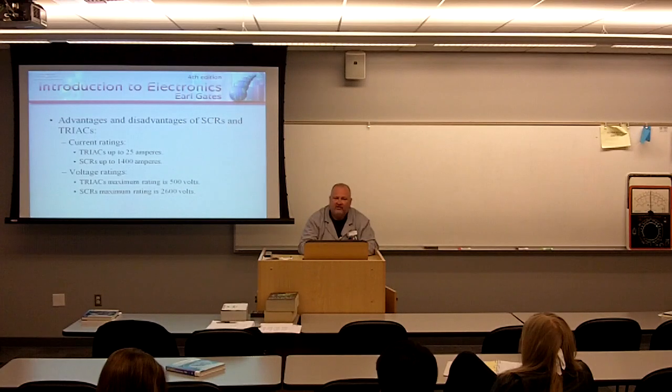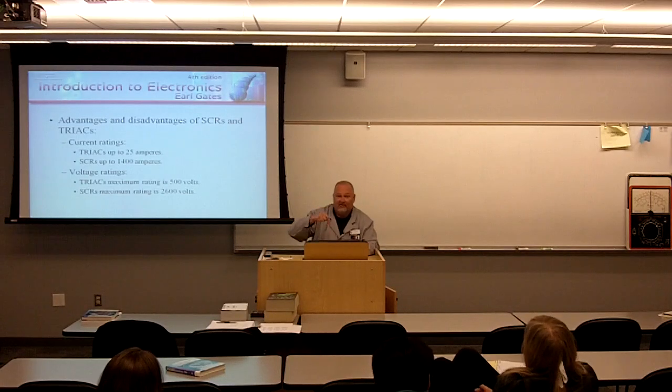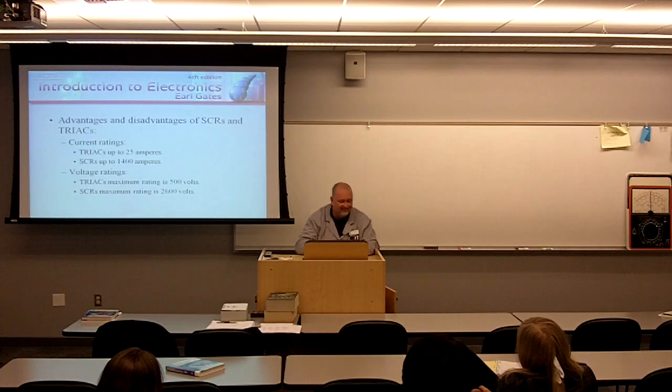Does anybody know the maximum current that goes to a typical residential connection, your home? How many amps? Do you know how many? Some might. An older home might. Most of the newer homes, the standard is a 200 amp box. So with an SCR that's rated at 1,400 amps, you could control 7 homes with no moving parts. That'd be pretty cool. You wouldn't even hear a ka-chunk. You just hear silence.